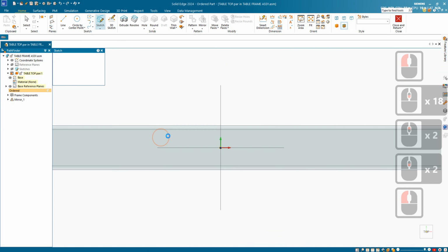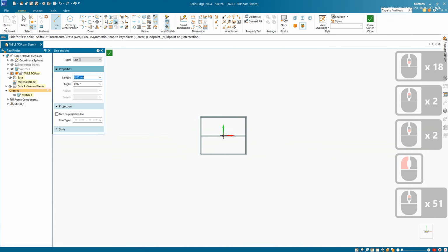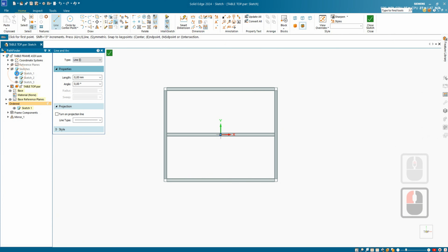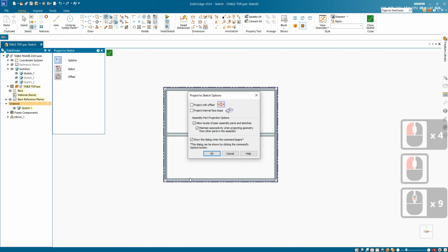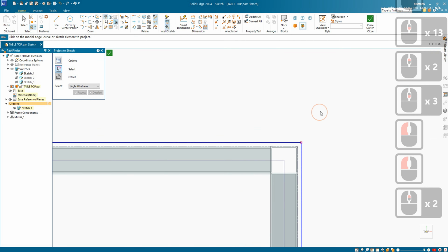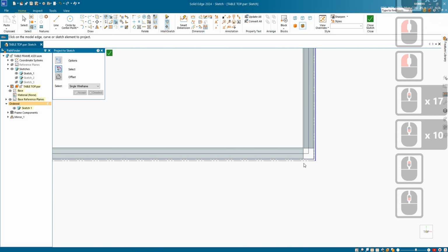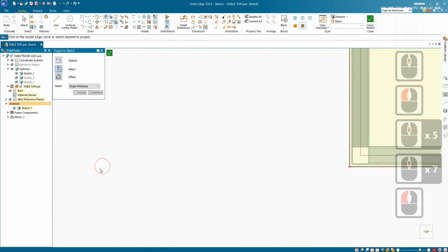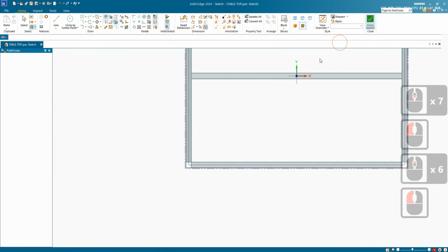Now we are creating a part in the assembly environment. So I'm just gonna switch on the sketches that I had done previously so that everything is being driven off of those same sketches. So if you change the dimension of the first sketch size, everything will update, the top and the frame and everything that's linked to that will update to those sizes.